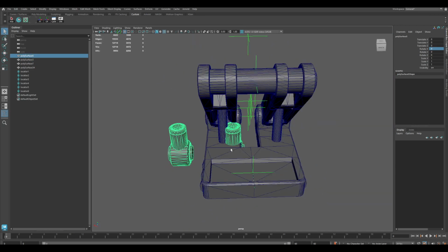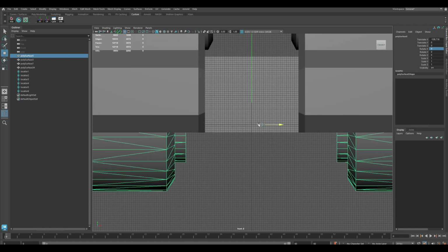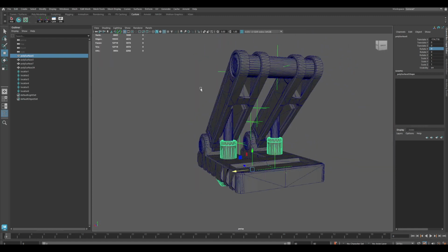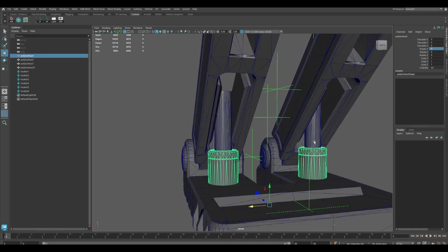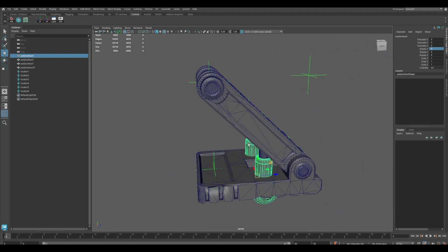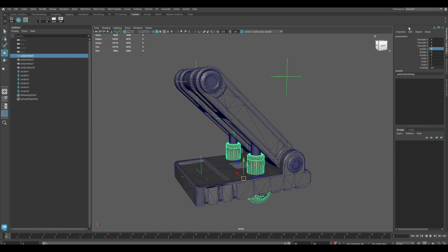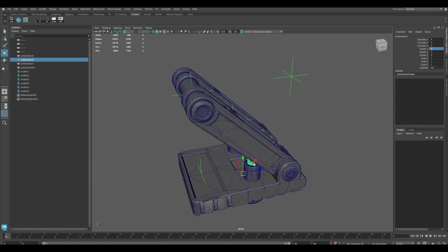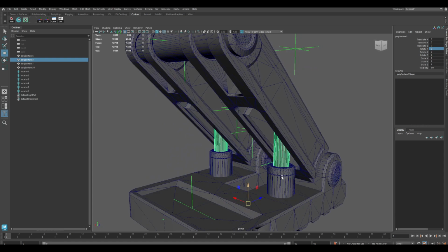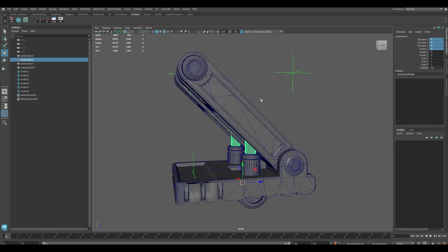And now you have both of the suspension parts exactly in the middle with all the values frozen to 0, 0. This is the easiest way that we are going to create our constraints later. So make sure that for these parts of the suspensions, they're facing directly to the y-axis and that they have 0 coordinates for translate and rotate.